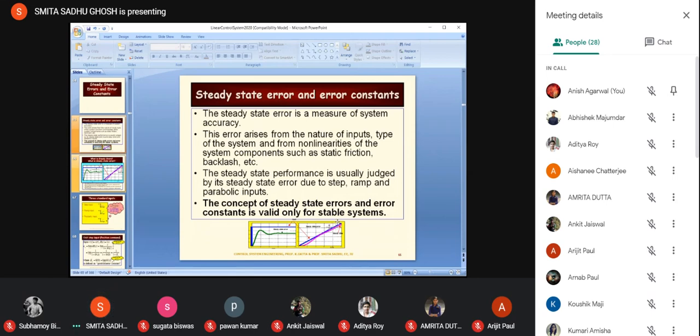And even if the input is following the ramp and keeps on increasing, the output would also keep on increasing, following the ramp, but that constant difference with the input would still remain. So that is implying the steady state error. Somebody may argue, ma'am, here the steady state is not reached at all. No, what I mean is that it is the difference with the input which has been applied. So if that difference with the input is constant, I say a constant steady state error is present,